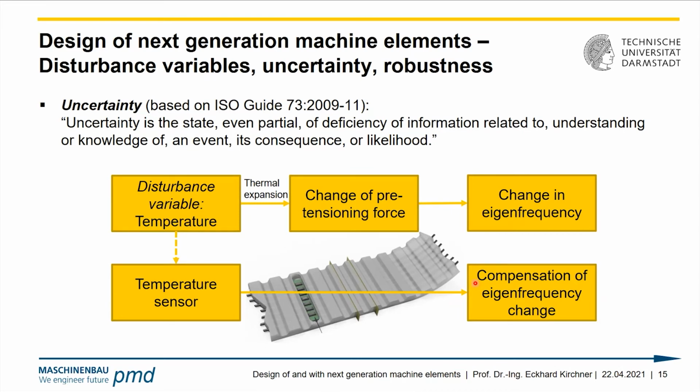So more stable with regard to the thermal effects is the system with the spring load on one pulley. For the system with the two rigid discs, we have a more pronounced change, and probably it's easier to detect changes with that system because we have a much higher sensitivity with regard to thermal influences.